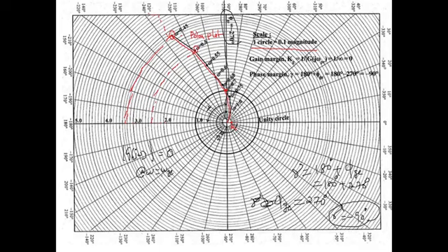Sorry, could be infinity, because we don't have any value. We don't know where the value could be, right? So it may happen that the value could be infinity. So if it is infinity, what is the gain margin? Gain margin equals 1 divided by that infinity. 1 by infinity is what? 0. So this is the final answer, right? So gain margin equals 0. If you want to convert it, you can convert it, so that is also 0 degrees. So this is how we have to complete the problem, right? Thank you.